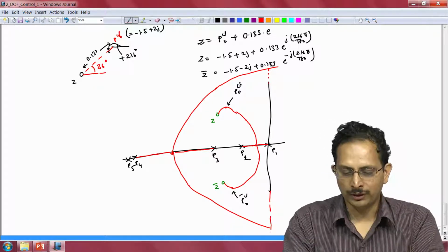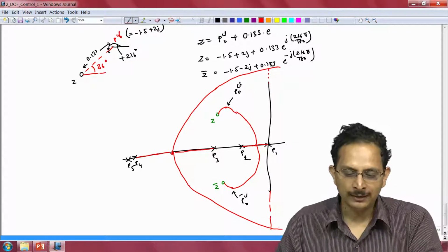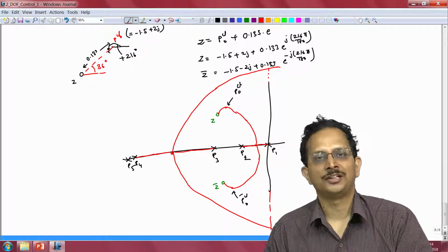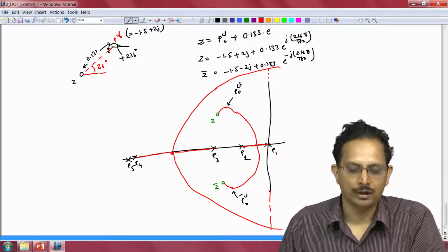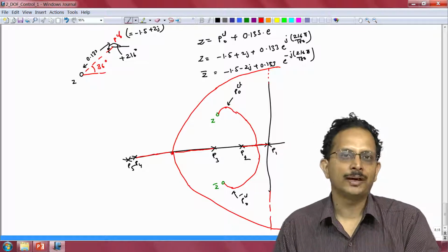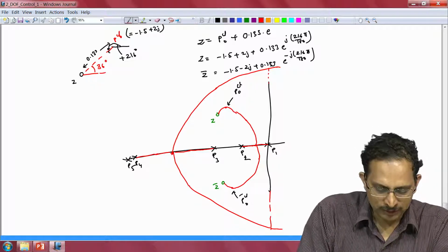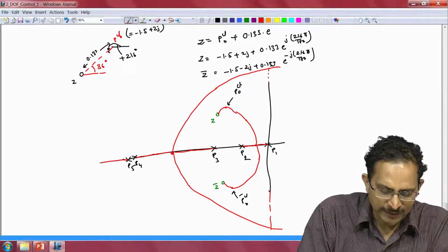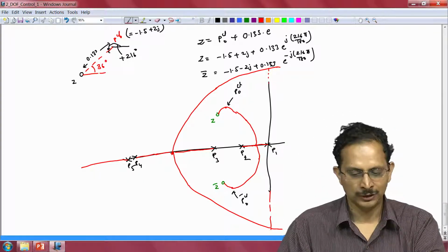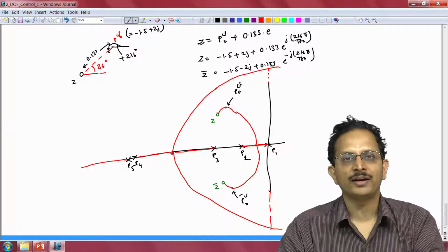imaginary axis. So if the gain of the overall open loop system is more than this particular value, then one pair of poles are going to lie on the right side of the imaginary axis, or we would have an unstable system on our hands. Now altogether we have 5 poles, so we need to have 5 branches to the root locus, and hence the 5th branch would start from the point P5 and head towards its left towards s is equal to -infinity along the real axis.